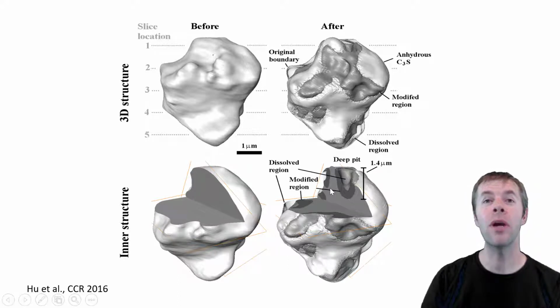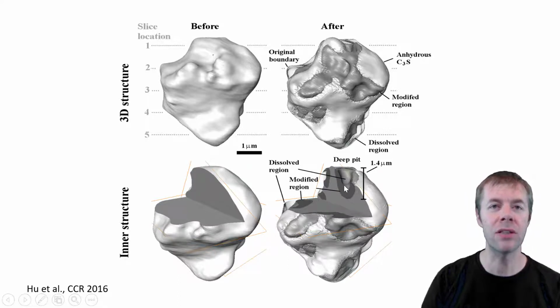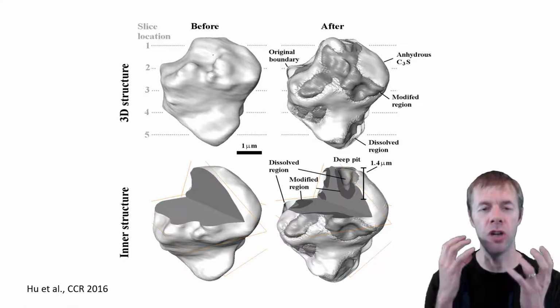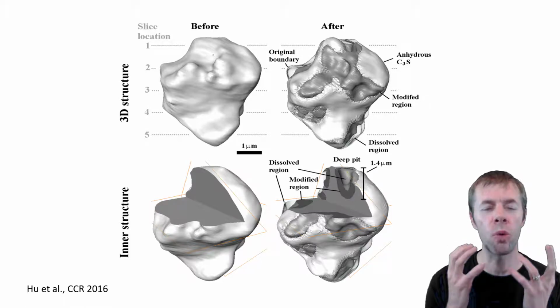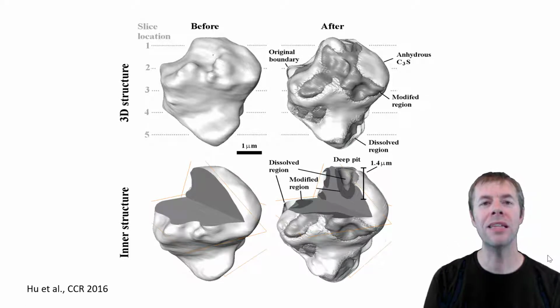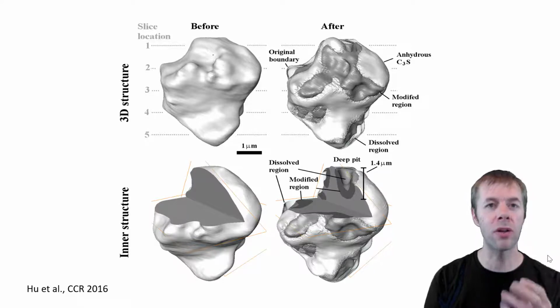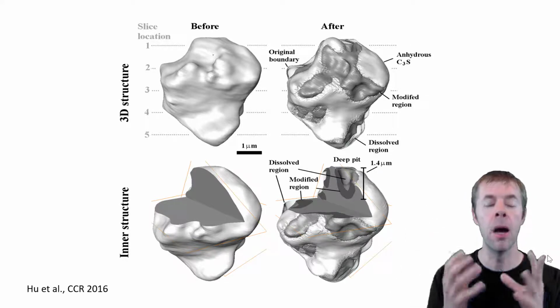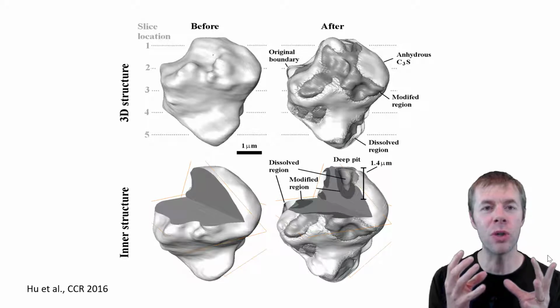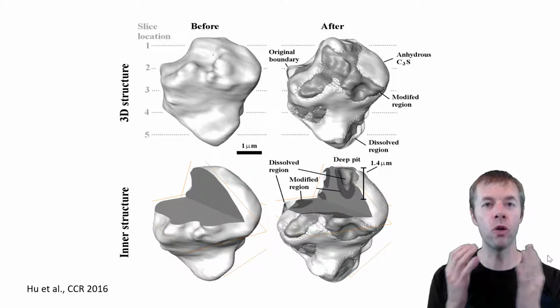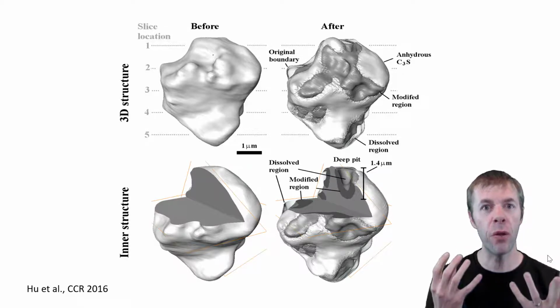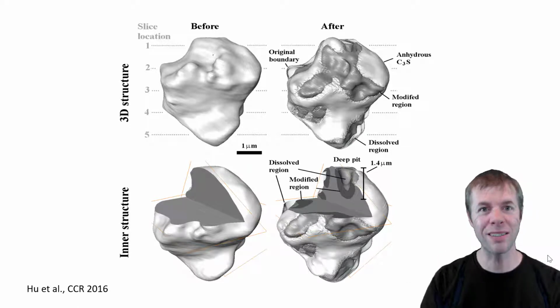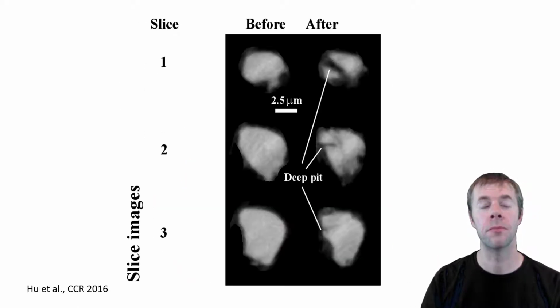Yeah, and we can look inside of it, and we can see these pits being dug, these holes being dug inside. This is an example of a non-uniform reaction that's happening inside these cement grains. These big pits are an example of hydrolysis, of the water molecules digging, but they're only digging in certain regions and not in others. And those pits are filling with hydration products. What? I know, let's see.